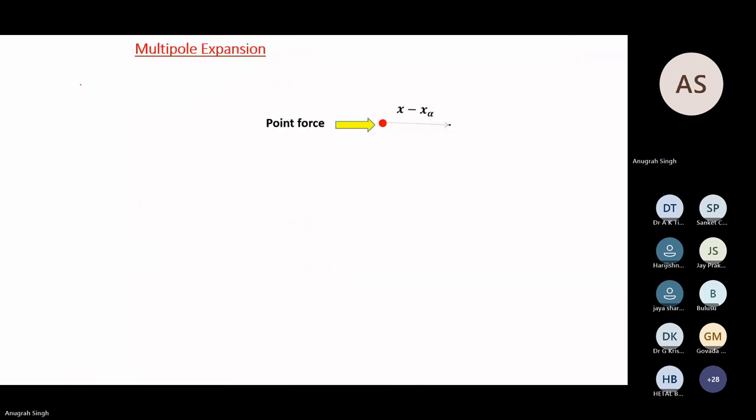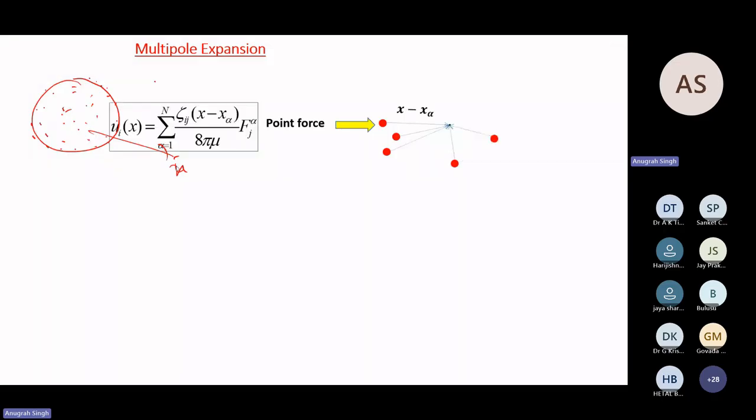That means it constructs a particle by distributing point forces. A small tiny force is creating some disturbance. You can distribute this tiny force field on the sphere. They all will create disturbance at some certain point, right? So it's built from the point force solution because the point force solution was straightforward, right? This is the Stokes limit.